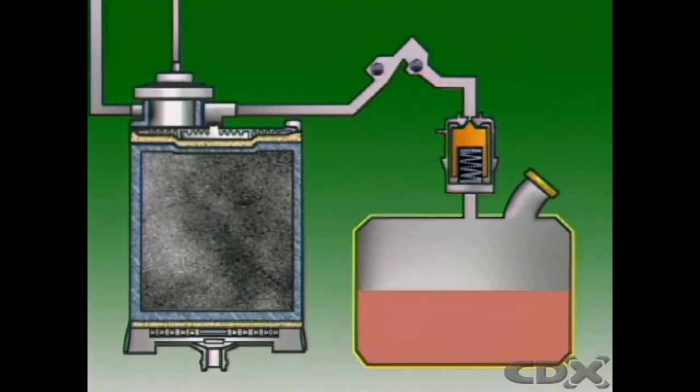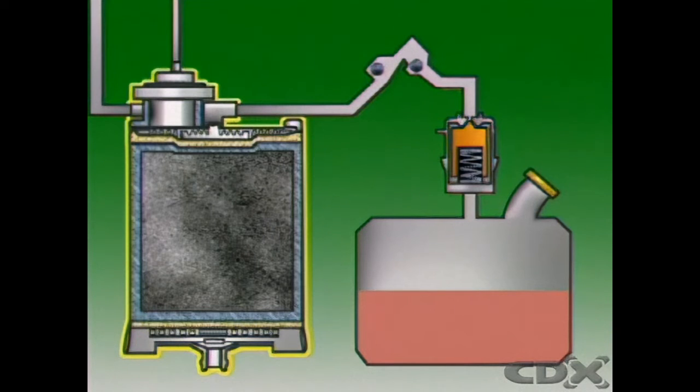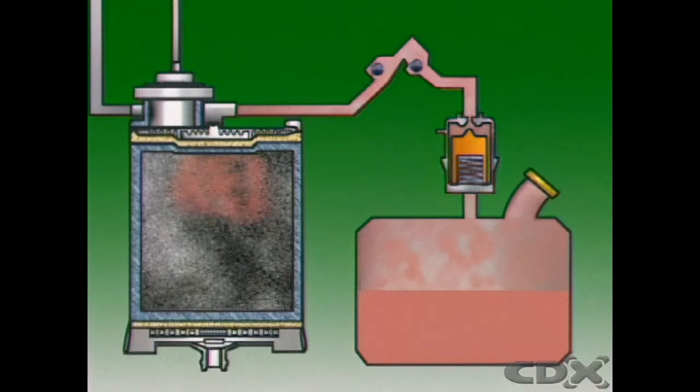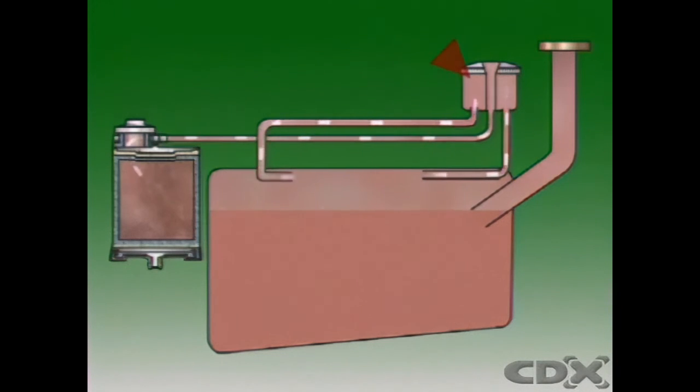Vapor from the fuel tank is trapped in a charcoal canister and stored there until it is burned in the engine. A vapor or vent line with a check valve connects the space above the liquid fuel with the canister. This valve opens when pressure starts to rise and lets vapor through but not liquid. Liquid fuel closes the check valve and blocks the line, stopping liquid fuel reaching the charcoal. Some systems have a small container, called a liquid vapor separator, above the fuel tank. It also prevents liquid fuel reaching the charcoal.